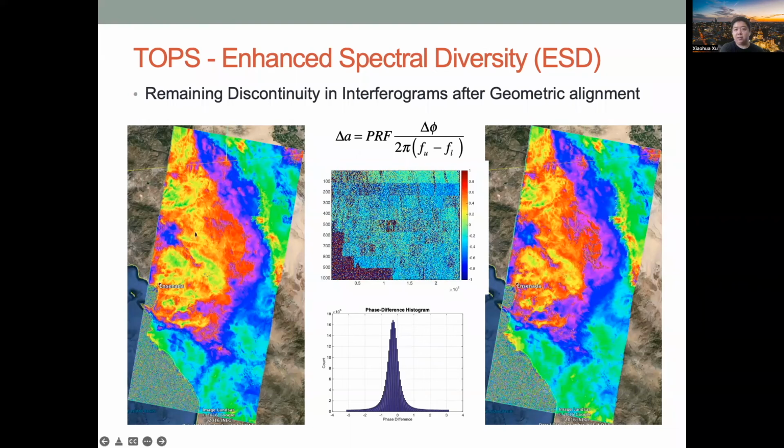Some of these discontinuities are real, like orbit errors or misregistration, but you have to notice that this azimuthal motion may not be just from the orbital errors. It could be from real tectonic motion. If your targeted area is something like an earthquake or strong subsidence that happens in a short period of time, it's probably okay. But once you start to look at small signals at tectonic scale, the problem will likely show up.